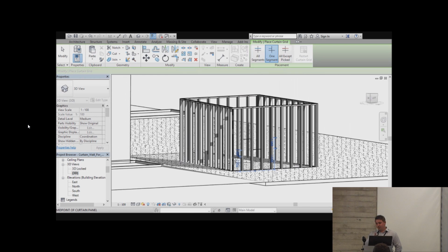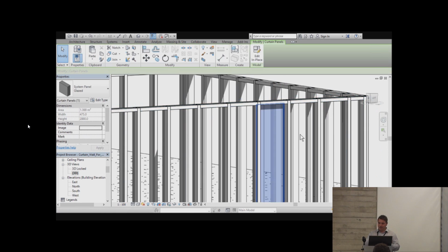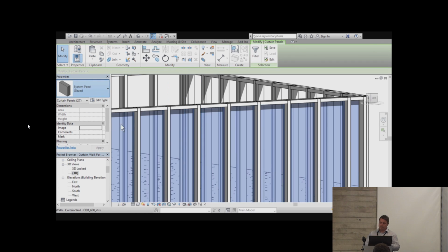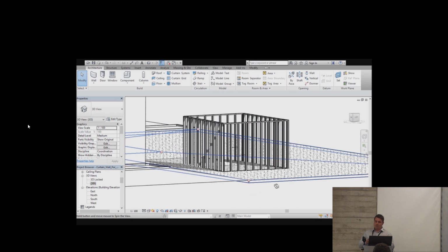So using the applied grid line, again, going to just one segment, you can see here I could stagger it and I place little lines to host mullions. And again, at the end, I'm just going to select all of the glass in it and just remove it. So as I say, it's quite a simple one. That's just a way to speed up working with Curtainwall.